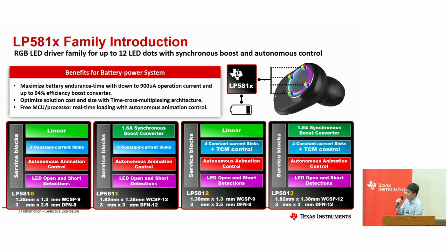The first one is that with our integrated boost converters, we can help maximize battery endurance time with down to 900 microamperes of operation current on the LED driver and up to 94% efficiency when you're doing the boost converter to generate a higher Vout for the LEDs.